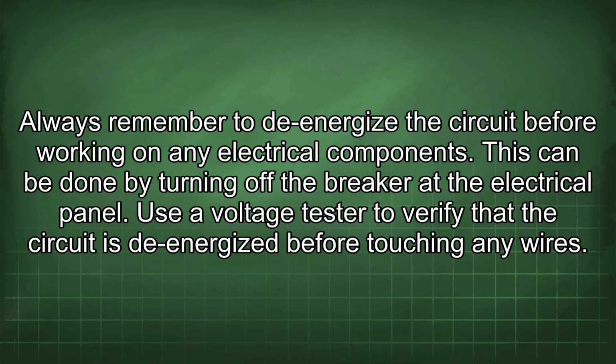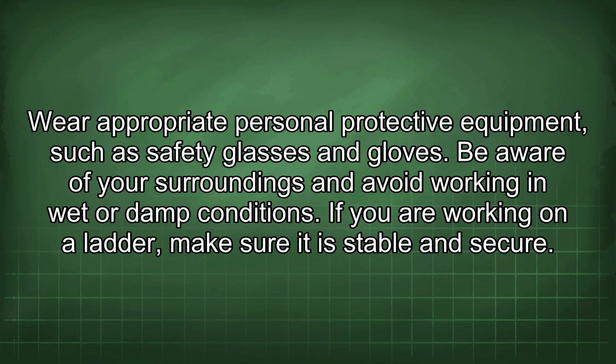Always remember to de-energize the circuit before working on any electrical components. This can be done by turning off the breaker at the electrical panel. Use a voltage tester to verify that the circuit is de-energized before touching any wires. Wear appropriate personal protective equipment, such as safety glasses and gloves. Be aware of your surroundings and avoid working in wet or damp conditions. If you are working on a ladder, make sure it is stable and secure.